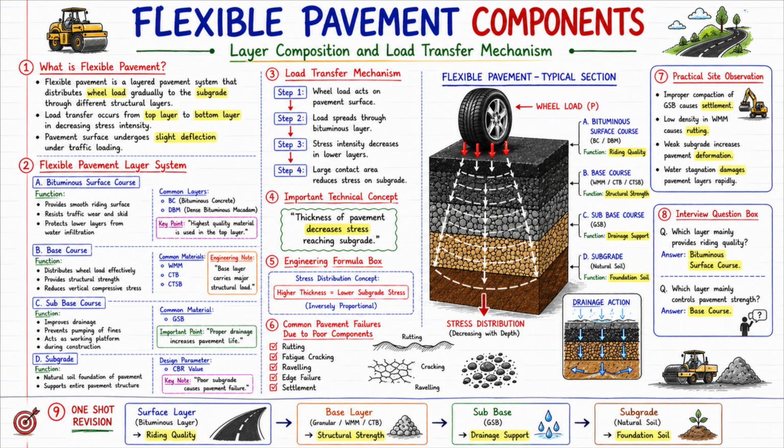See sub-base course. Now comes the sub-base. Its function: improve drainage, stop the pumping of fines, and provide a working platform during construction. Now here is the common material, GSB. The important point is written below. Proper drainage increases pavement life.